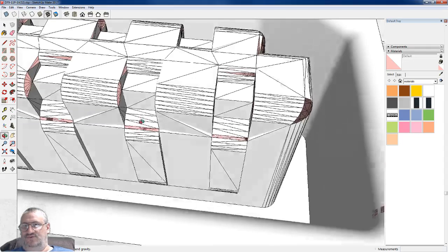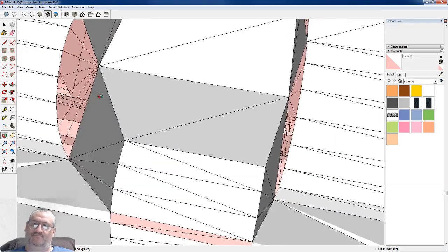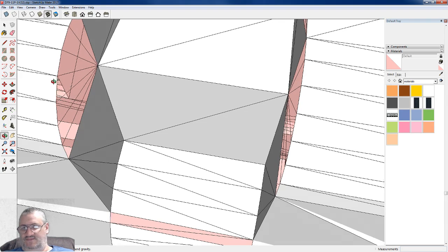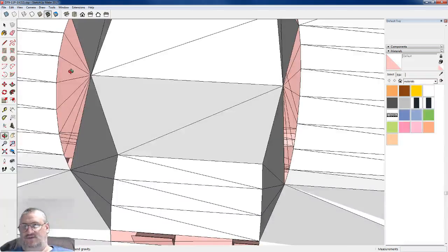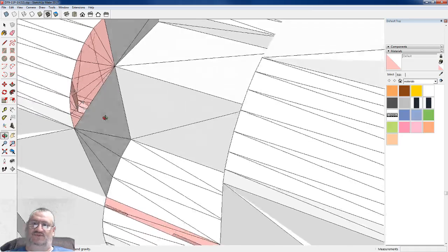And the reason these faces are not filled is because one or more of the, in this case, 3 points that make up the shape are not considered to be in the same plane. Now, I'm not sure how that works with the three-sided thing. With 3 points on a shape, it's got to be all in the same plane. But for some reason, it doesn't think it is, and so there's no faces there.